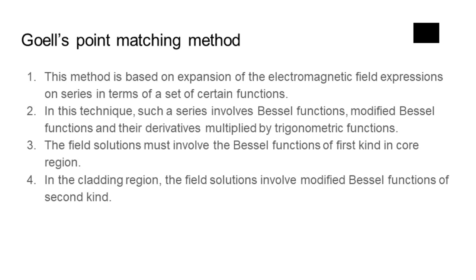Another new numerical method, based on the mapping of the molecular dynamics of extraction of extreme eigenvalues and the corresponding eigenmodes, has been applied for the scalar and semi-vector mode analysis of arbitrary shape optical waveguides by Noro, who has suggested analyzing the modeling and optimum design of lossless optical waveguides using this method. The point matching method involves a rather exhaustive and formidable numerical computation.